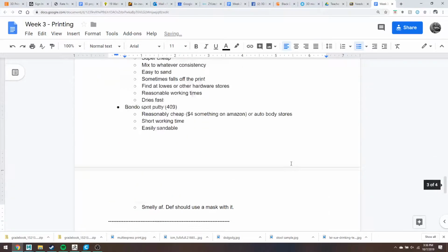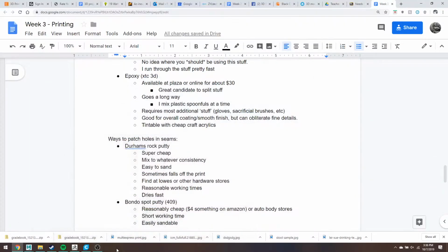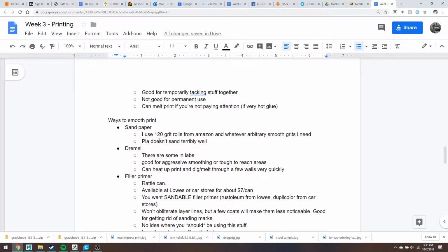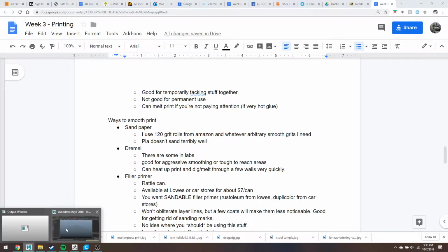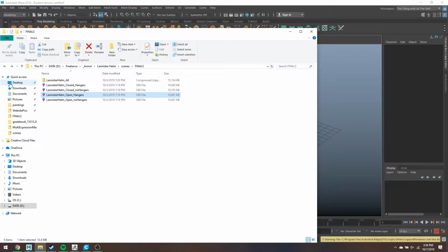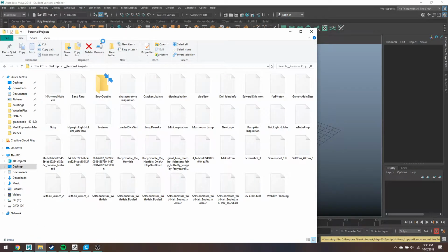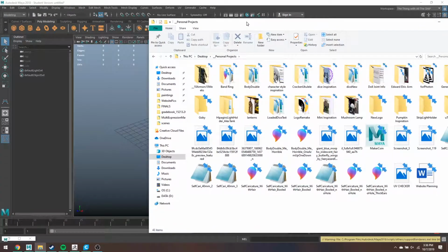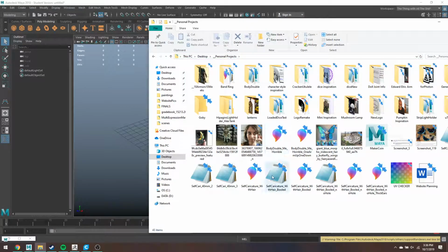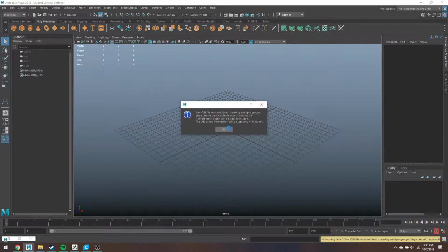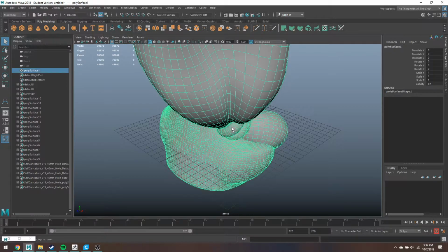Guys already, hello. Great. I assume you already know about Booleaning stuff in Maya and how to do that. I want to show you some other ways to do it in case Maya is, again, being evil. So let me find, I have somewhere on my computer, this ridiculous little head model that I use for everything. I just want to find the separate one so I know which one it is.